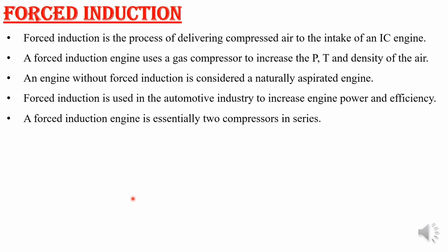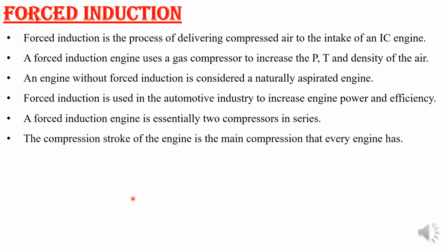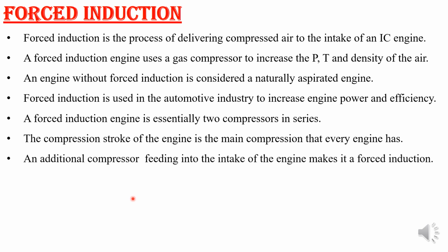The compression stroke of the engine is the main compression that every engine has. An additional compressor feeding into the intake manifold makes the forced induction. So compression will always be there in the normal case of the engine, but along with that we are going to add one more compressor outside in the intake manifold, so that we are feeding the air at more than 1 atmospheric pressure. A compressor feeding pressure into another will greatly increase the total compression ratio of the entire system.